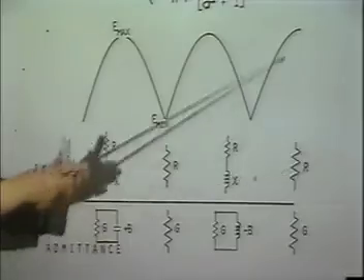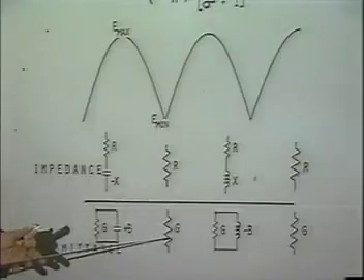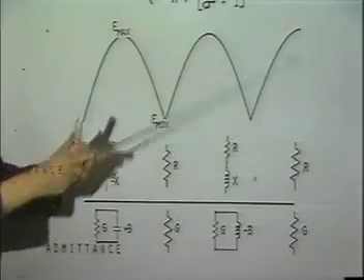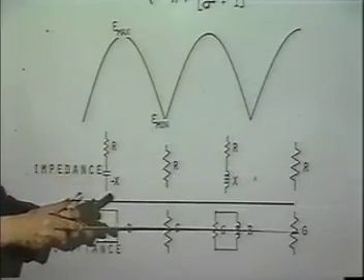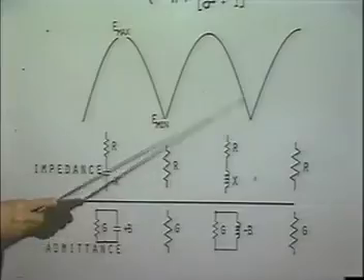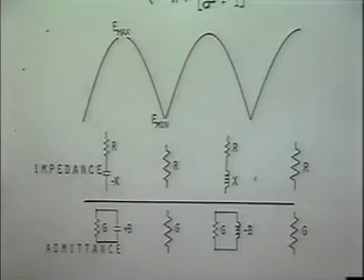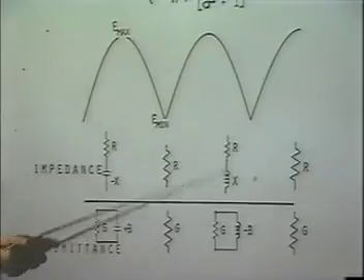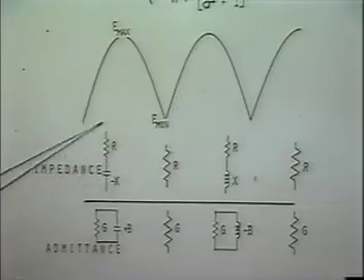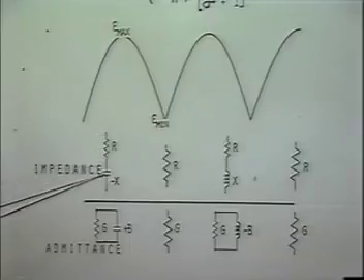Remember I said that pure resistance greater than Z0? Pure resistance, E minimum, R minimum, G maximum. Okay? Over here you have R max, G minimum, because they're reciprocals of each other. Anytime you travel on the transmission line between this minimum and this maximum, if this minimum does not go to 0, in other words, you don't have total reflection on the line, then you will have resistance and reactance in this area here. If you go at this point here, pure resistance again. Over here, anywhere from E max down to this point here, you have a resistance and a reactance.